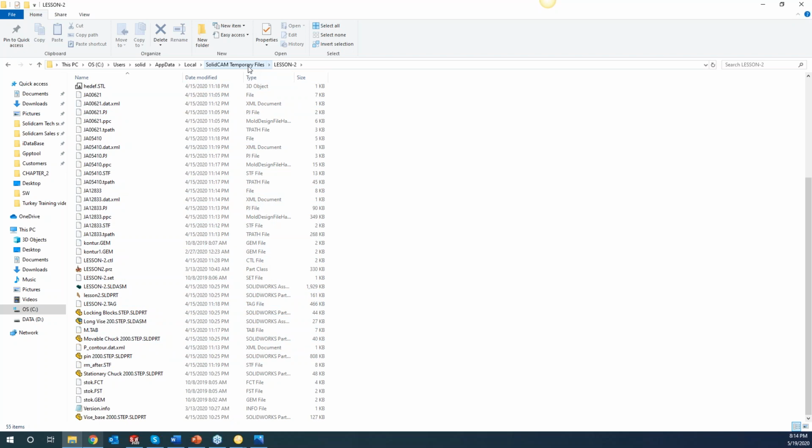So when I close out of this project, it takes that PRT file along with this folder, zips it all up into one folder, and saves it to the specific location that you specified when you first started that CAM project. Like I said, this was really designed for saving out on the network, so it eliminates any server lag and those long wait times to save and calculate when you're saving to a destination file. That is how it works, and I'll show you it in action.